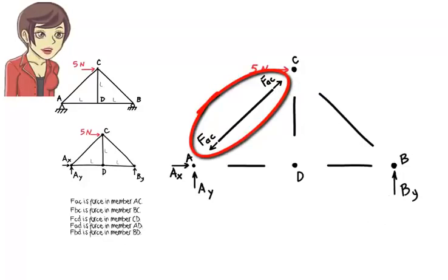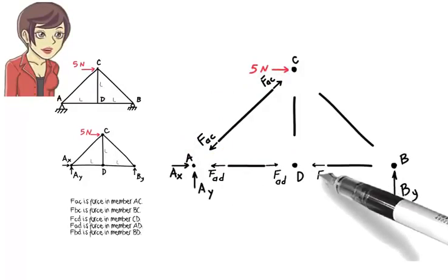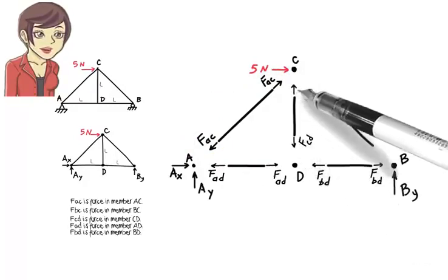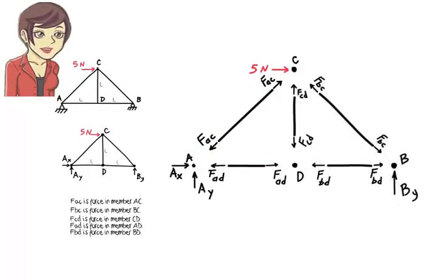The only force present in the diagram is the unknown tensile axial force in the member labeled FAC. I am going to draw the free body diagram for the other member segments in a similar manner. Each member is assumed to carry an unknown force. The member is assumed to be in tension.